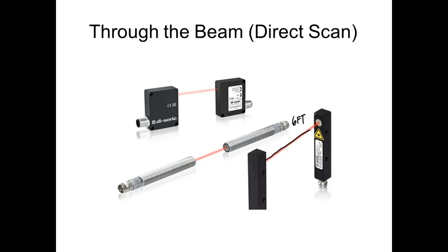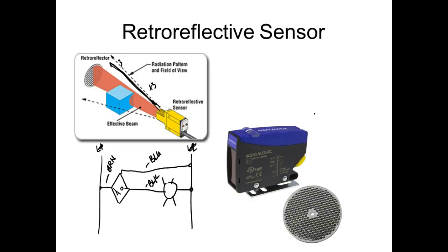So these are photoelectrics, by the way. The sensor that you have in your hand, we can run as a diffuse sensor, and a retroreflective is about the same. When you do your lab, you'll notice that with the retroreflector on there, you can go back like 8 feet and still break the beam. But when you take that retroreflector off and use it as a diffuse sensor, you have to get within like 6 inches before it triggers.